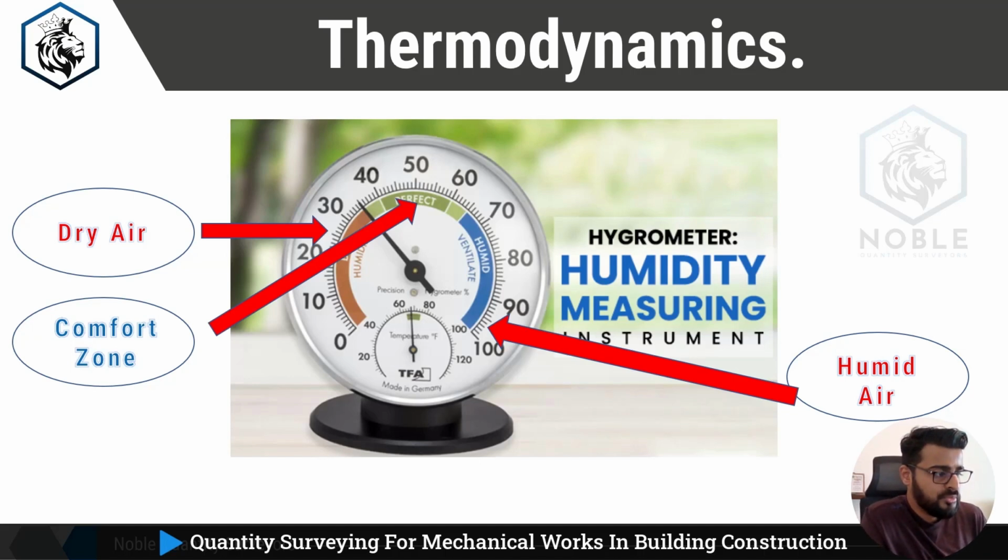Okay, so these are the three zones. 0 to 40%, which is known as dry air, is not good for human health. The next one is 40 to 65 or 70%, okay, which is known as the comfortable zone, required for human comfort. And the last one is 65 to 100%, which is known as humid air. Mostly the countries which are linked with the sea and oceans will have this kind of humid air, and that humidity has to be removed by our air conditioning system.